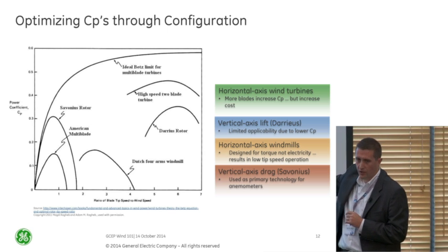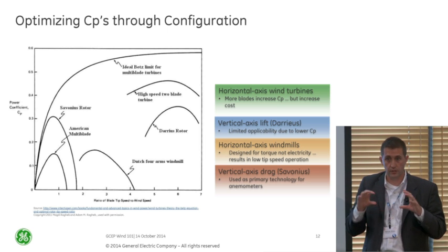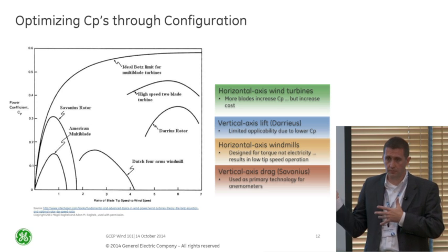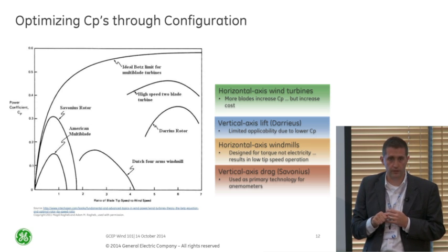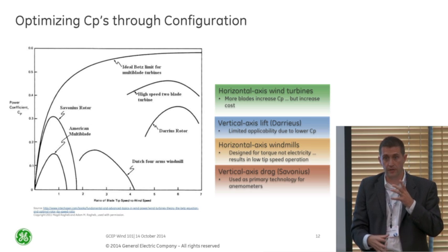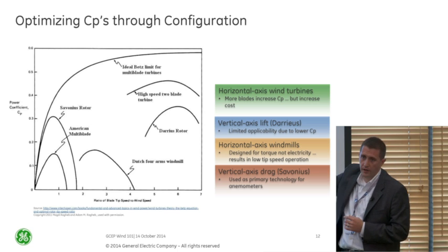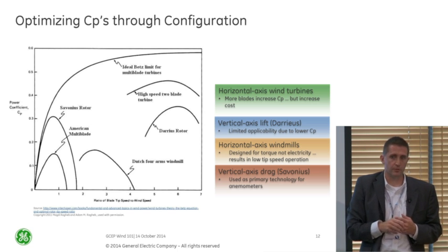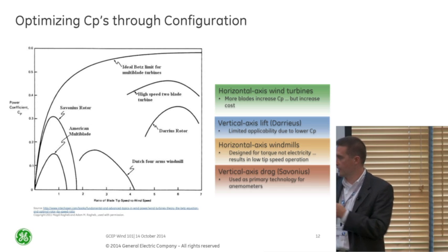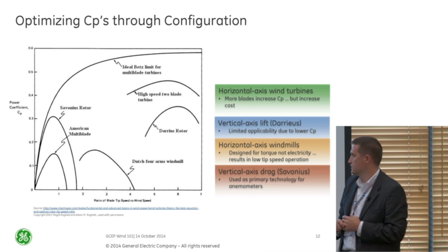So the only place you might see a Darrieus, and there is some active research going on, is for really large offshore wind turbine farms. I mean, not at GE, but at Sandia, they have a big program looking at vertical axis. The idea is I can have significantly lower loads on my foundation, which is a huge cost offshore, by going to this Darrieus rotor. I sacrifice some of my aero efficiency, but I can do that because I'm trading it off for a huge cost advantage. So that's the trade to shift down on this curve. You really need to have some sort of huge cost advantage.